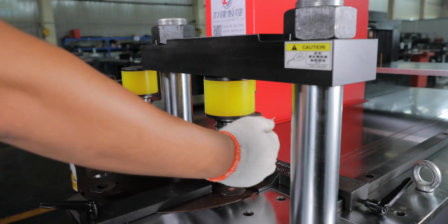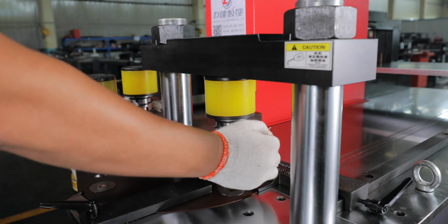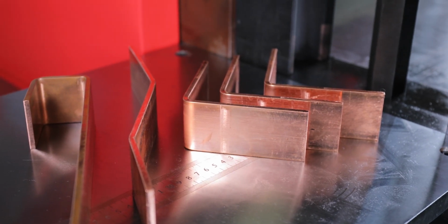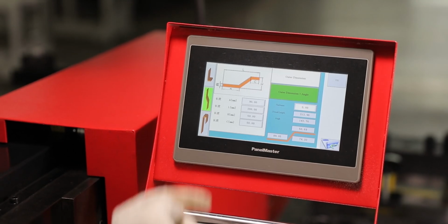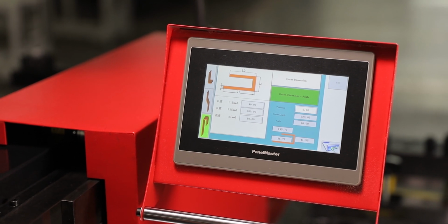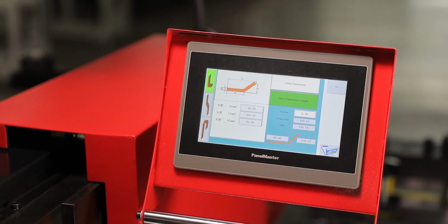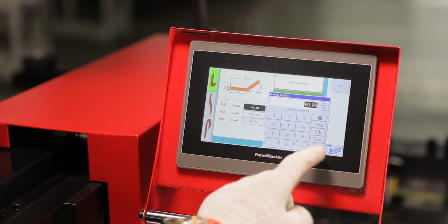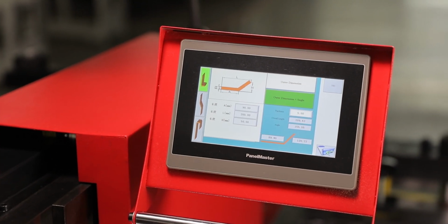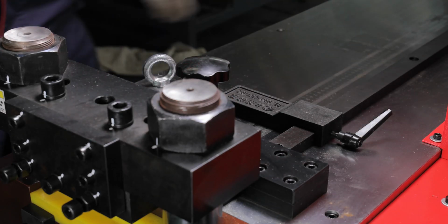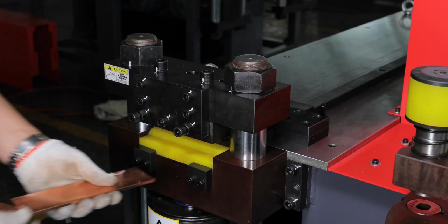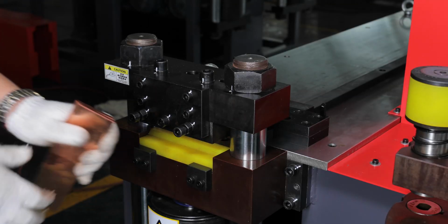The bending station is divided into 3 operation modes: L-shaped, Z-shaped and U-shaped. When working, only need to select the corresponding simulation graphic and input relevant parameters, and the bending process can be conveniently and quickly performed. The cutting unit of the machine is a double knife hedge cutting, and the cutting mouth is smooth and cutting without waste.